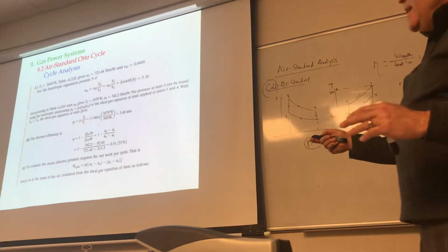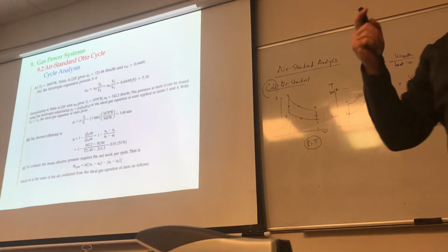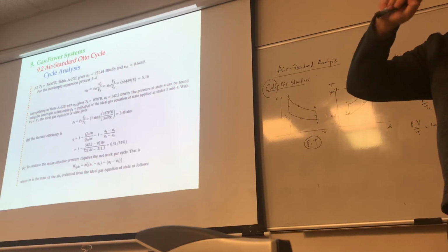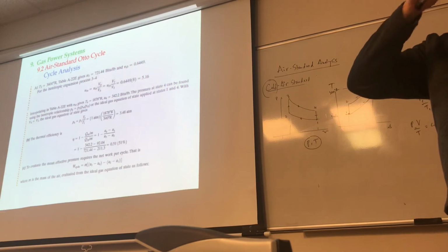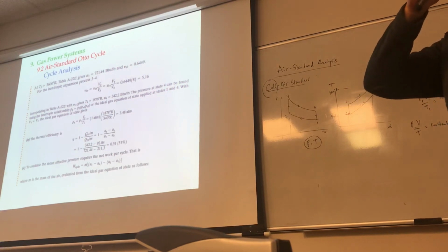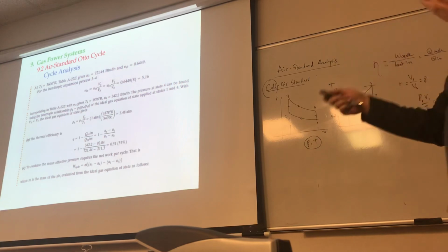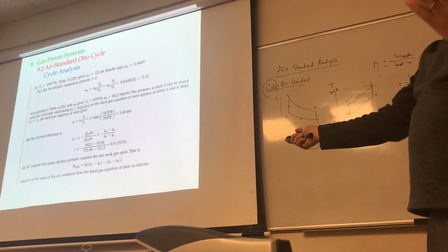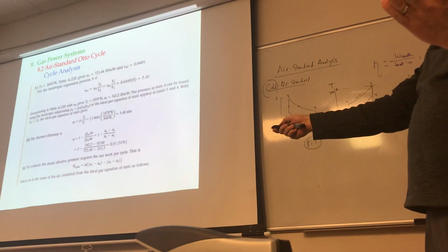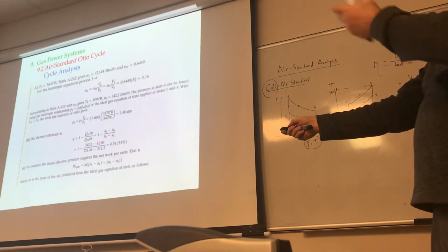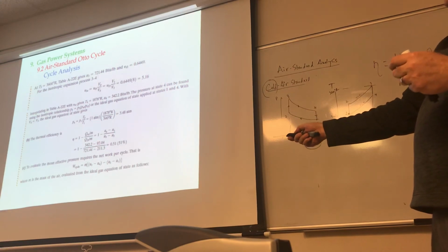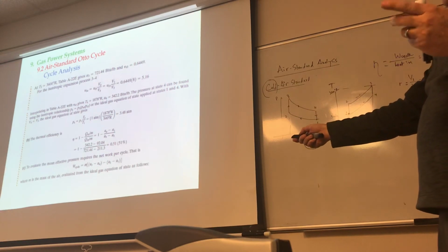Now, by the time you reach this point, for those 4 states, you know the pressure, the temperature, and the internal energy. That's what an Otto cycle is all about. For each one of those states, you have the U values, the T values, the P values. After you get those properties, the rest of it is a walk in the park, right? For thermal efficiency, you just pick up the equation, put in the values, and find that thermal efficiency is 51%.